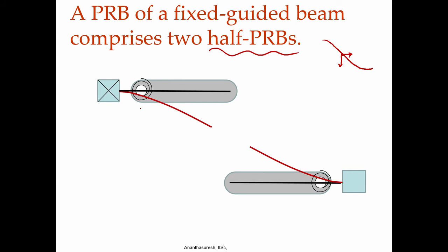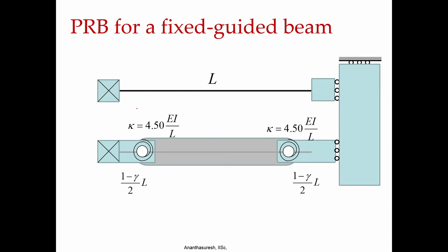So, we can replace the cantilever deformation with a pseudo rigid body model. Since there are two of them here, we make a model like this. So, we have the beam which is fixed and guided, and we replace, in fact what I have not shown here is the breaking of this. Okay, that is where the slopes of these two are going to be equal,